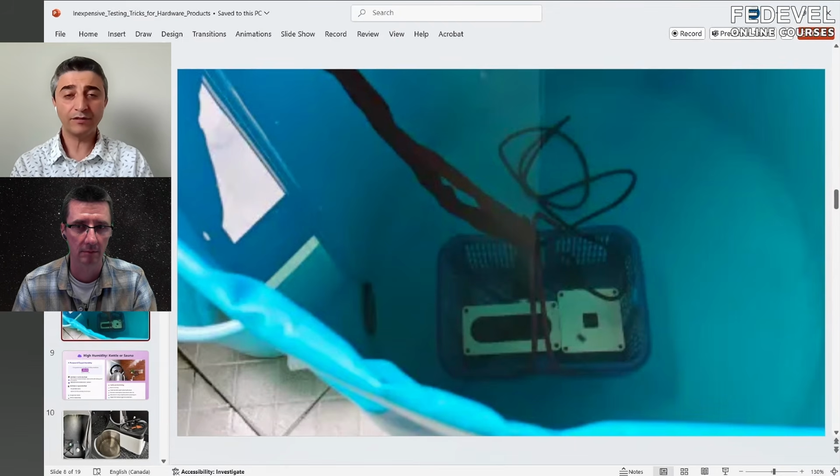I have done this tons of times in the past where we have a mini enclosure, probably the size of your hand. This is an industrial design that I wanted to verify in our lab before I go to the test chamber. So I have probably 2 or 3 holes. One of them was for the antenna. That was the weakest point. So we had to use a gasket. It comes with an antenna with an RF, like the SMA type. And yet it was because the enclosure was aluminum, so the hole was not uniform.